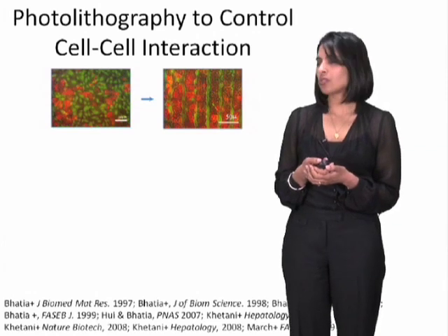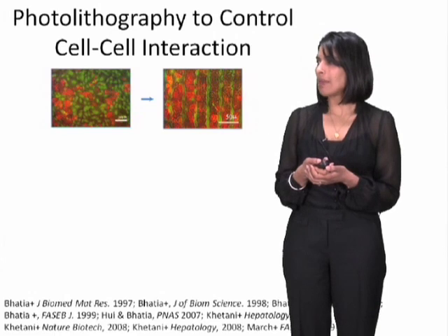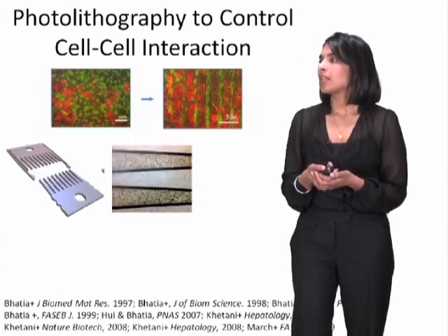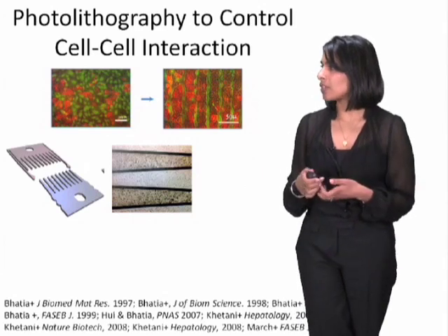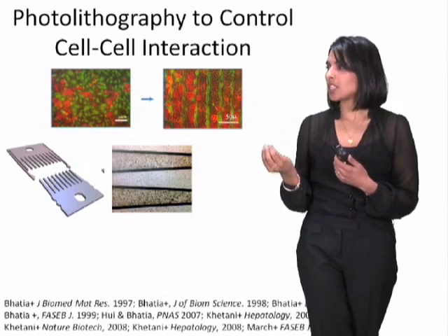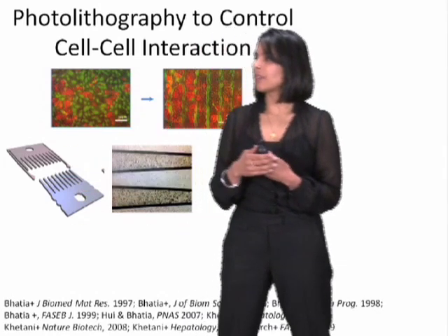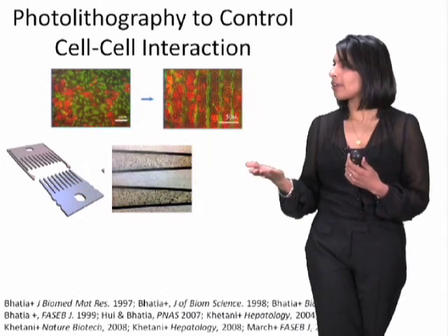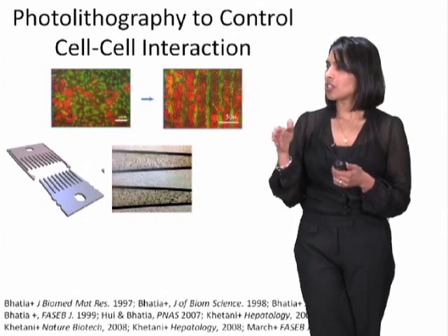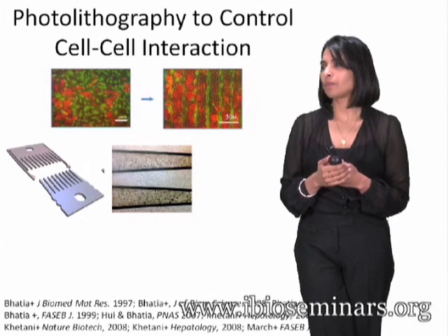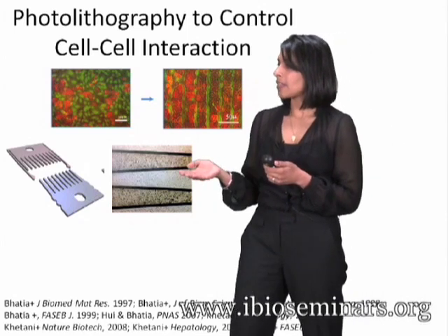In addition, we've been interested in using another version of microfabrication technology known as MEMS. In this process, instead of just making flat, planar patterned structures, groups have developed etching techniques over the years to etch crystalline silicon, like this part that you see here. This part is first patterned with light, and then deep reactive ion etching is used to etch out the structure that you see there. Using this part, we were able to manipulate our cells at the microscale.